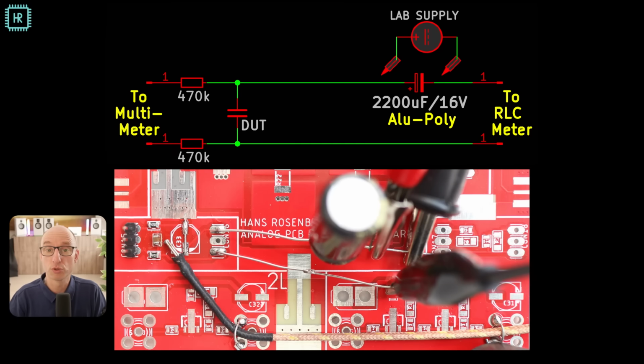So how do you solve that? With three changes. First, you use a really big capacitor, 2200 microfarad in this case. This means it's so big that even if the value changes, it's hardly going to affect the combined value of this capacitor in series with the DUT. Second, place this capacitor further away so it hardly heats up at all. We're only heating the area around the DUT.